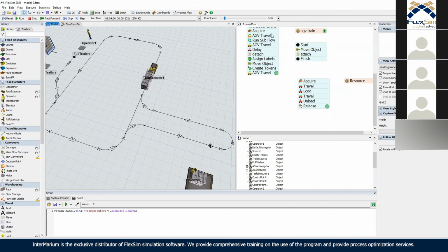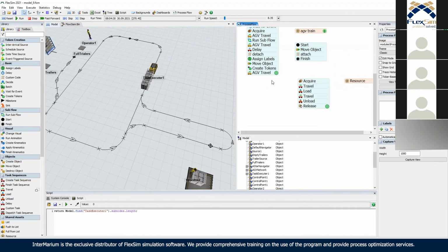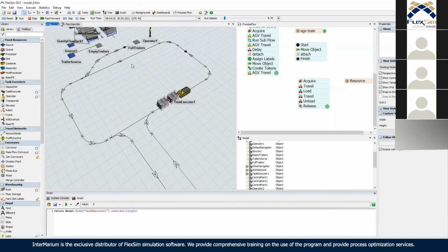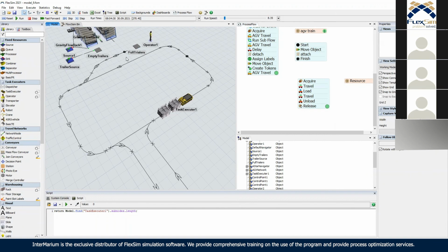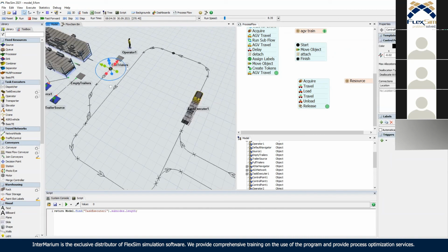Okay? With these AGV trailers and AGV, you would just use it instead of classic travel. So you can use the same logic, decide and then travel, and maybe chart the path alongside. This can be done however you want. What's important here is that each control point has information about the max allocation. It's here. Okay? So whenever you make a travel to this point, no other AGV can go there because the max allocation is 1. Yeah?